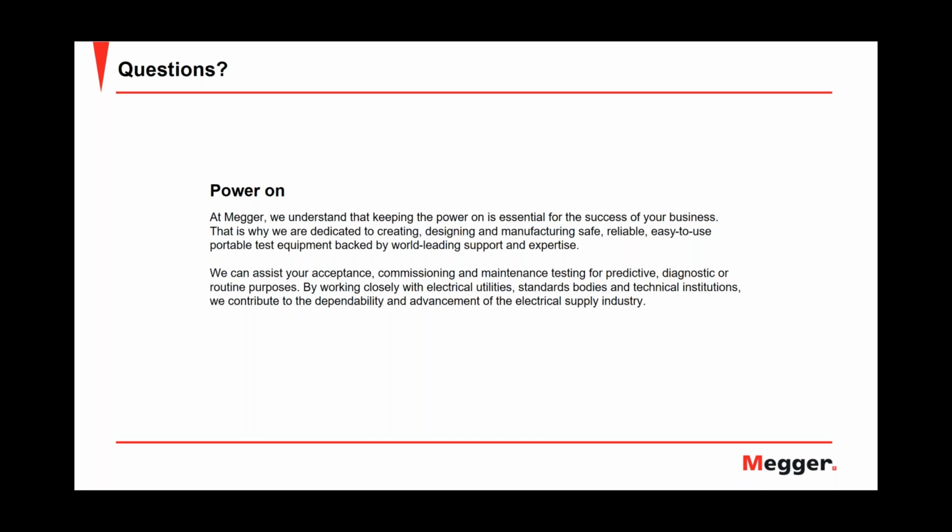First of all, he explained in the basics this whole voltage classes, and pretty much explained what RMS AC voltage is associated with these voltage classes, and that the actual main insulation of the cable is never stressed with this kind of nameplate system voltage, because that is phase to phase, but the main insulation is always stressed with U0, the phase to ground voltage, the conductor to shield voltage, so to speak.